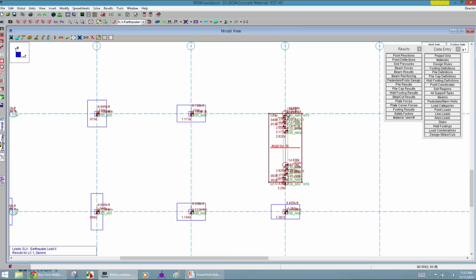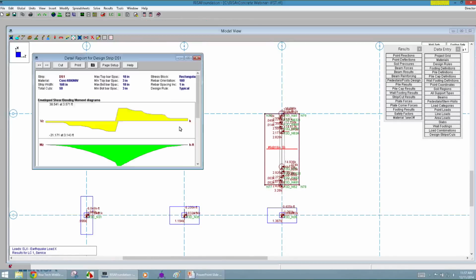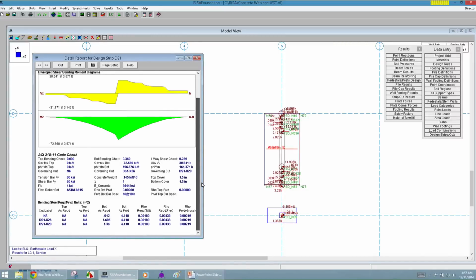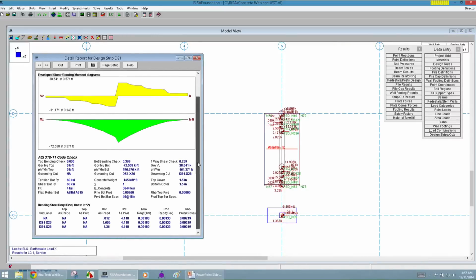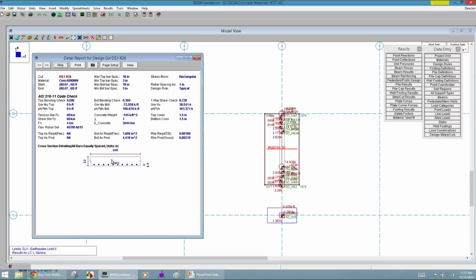And here we see this is also basically what I mentioned is a slab. So we're going to get the same information on this strip footing as just a slab. And so when we look at this, we just see the reinforcement design based on the slab right here. So again, just like we saw on top, it gives us the number 6s for this direction. Internally, we're cutting cuts right through there, just like we saw in RISAFloor ES. And so those cuts are listed directly like this here, just like in RISAFloor ES.